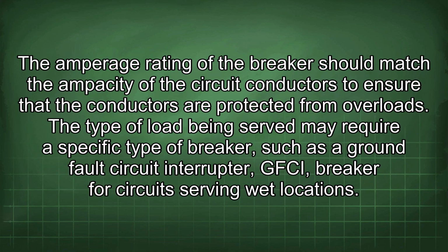The amperage rating of the breaker should match the ampacity of the circuit conductors to ensure that the conductors are protected from overloads. The type of load being served may require a specific type of breaker, such as a ground fault circuit interrupter, GFCI, breaker for circuits serving wet locations.